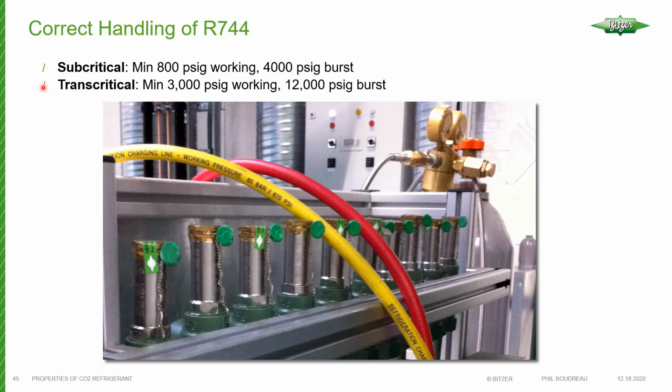And of course, if you're going with transcritical hoses only, which is probably going to be the case if you're working on booster systems where the high side runs for a few months of the year in transcritical mode above that critical point, you want to make sure that you're using the proper hoses.